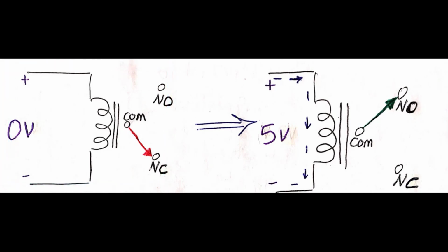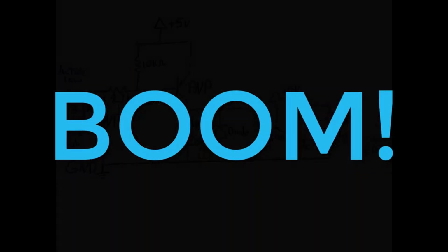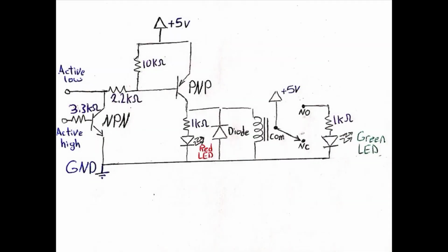So, when energizing its coil, you will hear a sound, meaning that the switch has moved from normally closed to normally opened pin. Boom, that's it. After having an idea about relays, let's have a look at its driving circuit.